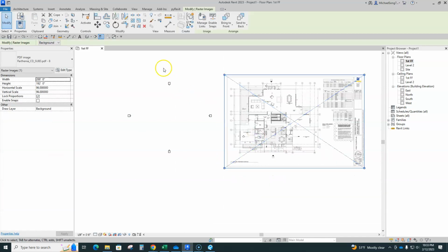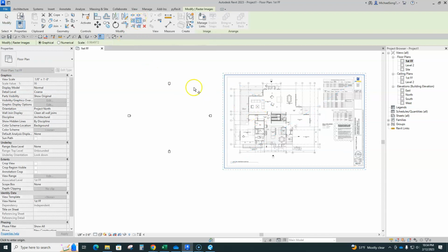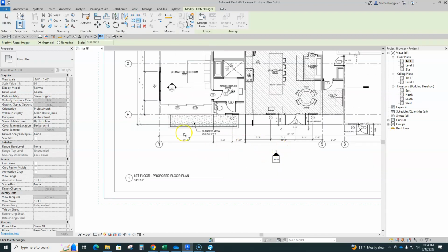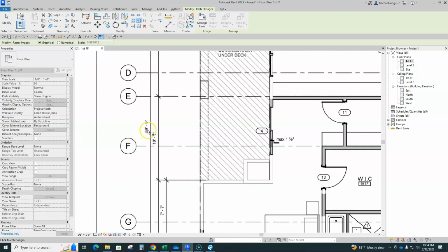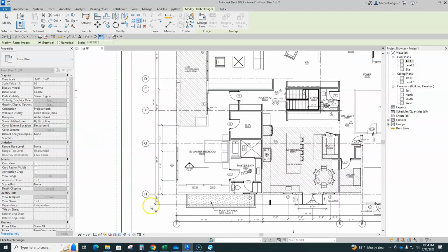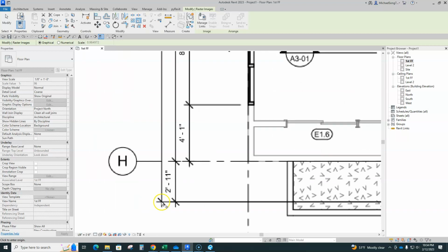So we're going to now scale this. You click on this item and hit this tool here, which is scale. Let's take a pretty big dimension. From here it is 59 feet 9 inches. I'm just taking the biggest number possible. So I'm going to click here.